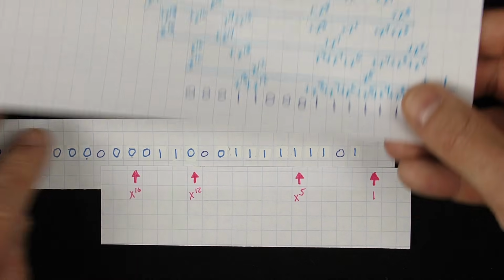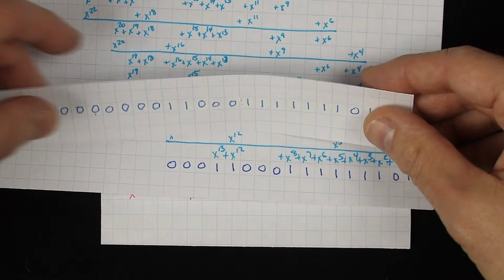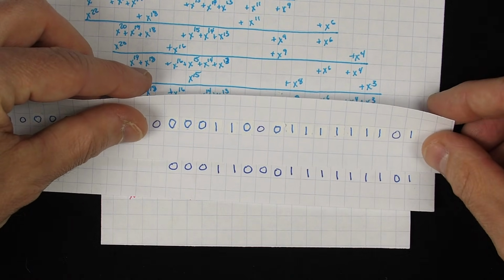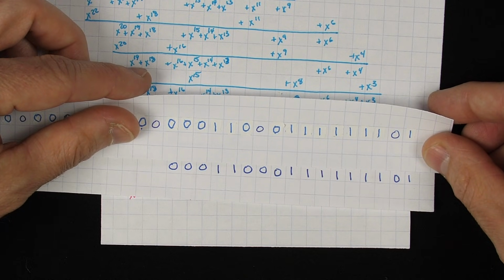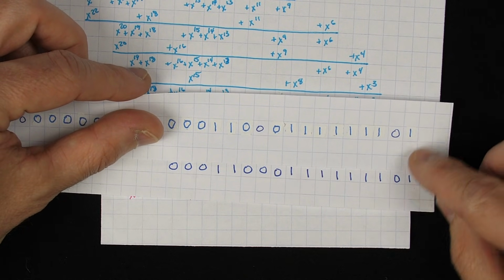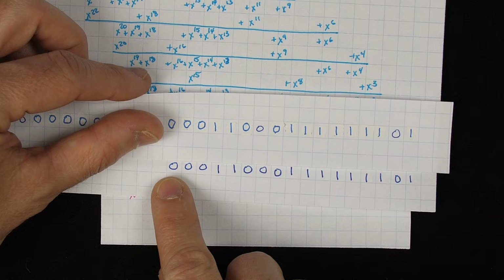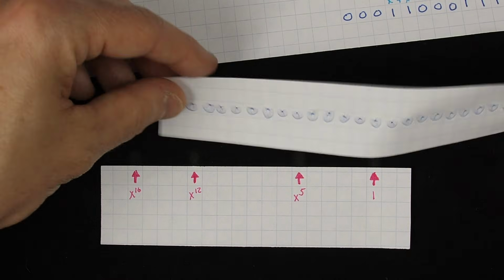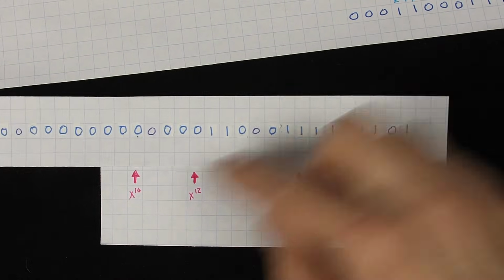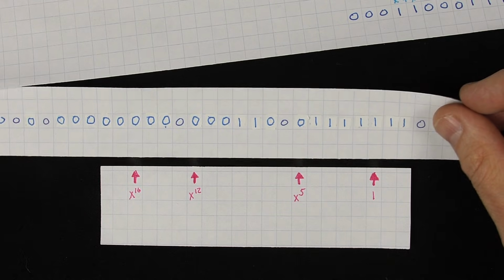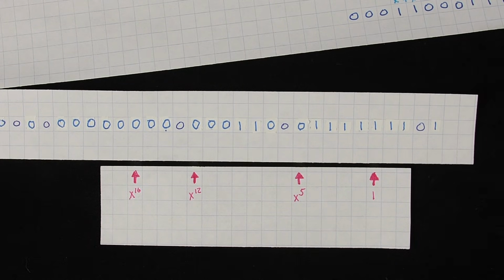So let's compare that to our long division here, and hopefully, if I did this right, yes, it looks like it's the same, doesn't it, right? So that's our CRC. And we're able to calculate it just by this sliding and conditionally flipping these 4 bits. And so those are fairly mechanical things that we ought to be able to do in hardware.